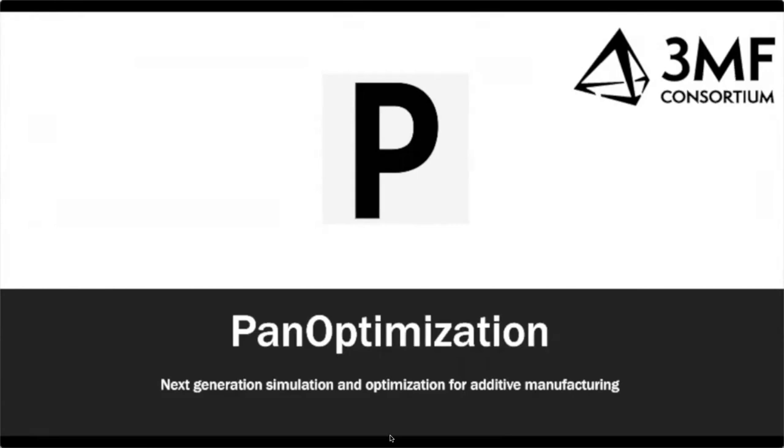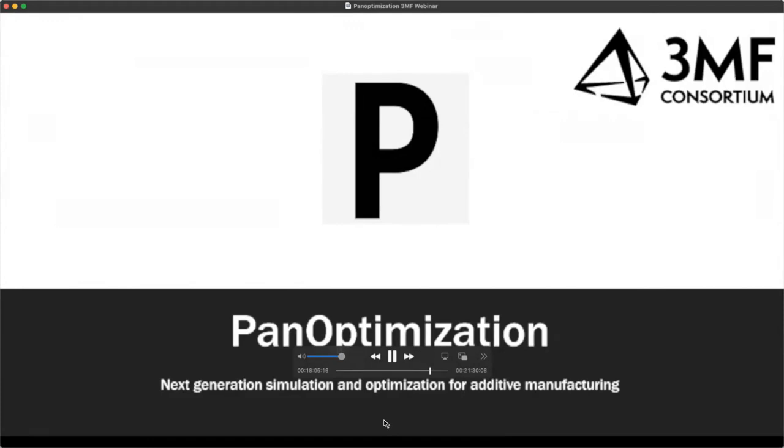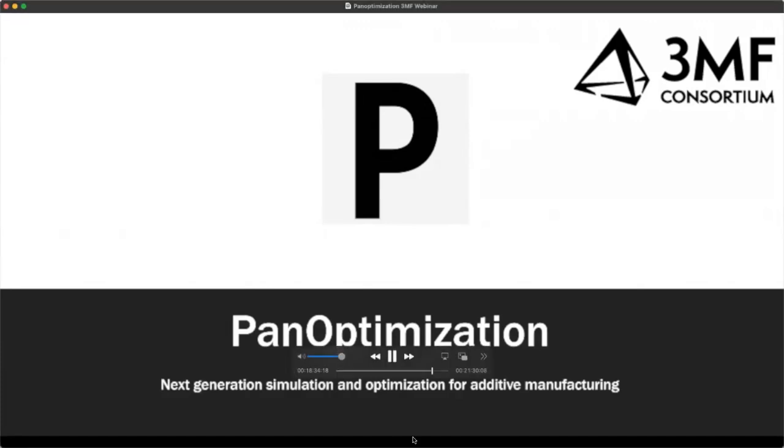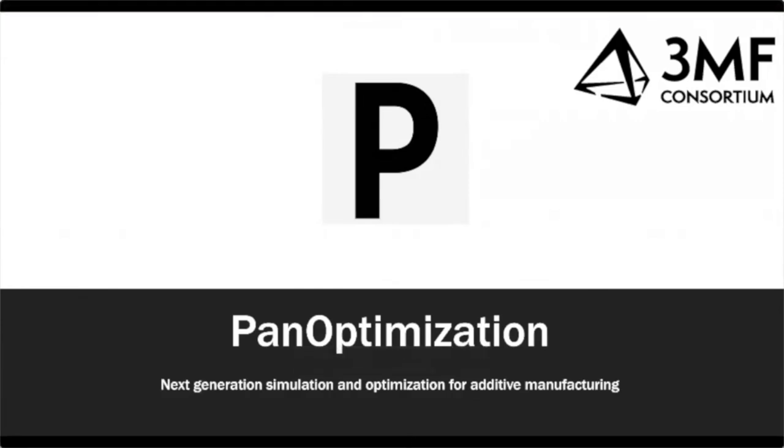is the same. Okay, so each user would need to make their own experimental data to feed that simulation, or is it something you provide to the customers? Well, the goal long term is to provide as much of it as we can. So we're working with about 5 different machine vendors to pre-calibrate default parameter settings for the machines. But if you're doing something with custom parameter sets, then we just provide you the CAD file for the samples, and you can build them on your own. They're small, like 10 millimeters high and 100 millimeters long. So they're designed so they can just fit on the edge of an existing build.